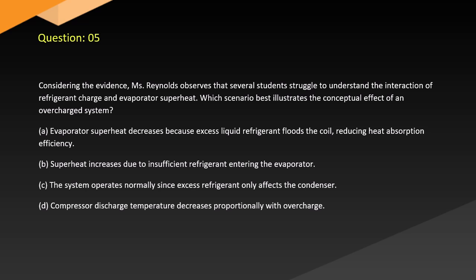A. Evaporator superheat decreases because excess liquid refrigerant floods the coil, reducing heat absorption efficiency. B. Superheat increases due to insufficient refrigerant entering the evaporator. C. The system operates normally since excess refrigerant only affects the condenser. D. Compressor discharge temperature decreases proportionally with overcharge.